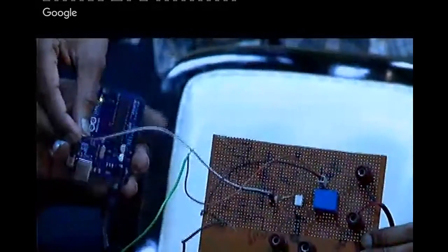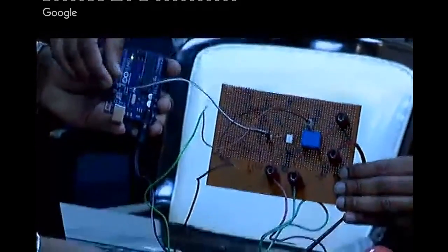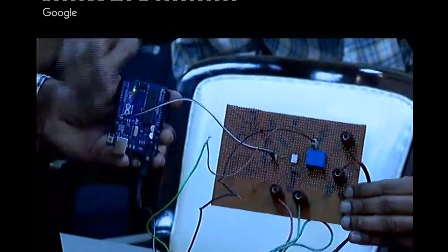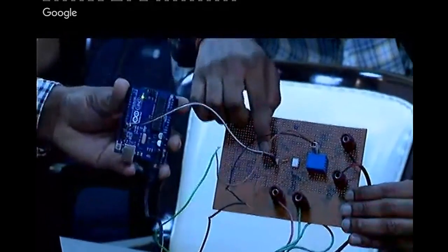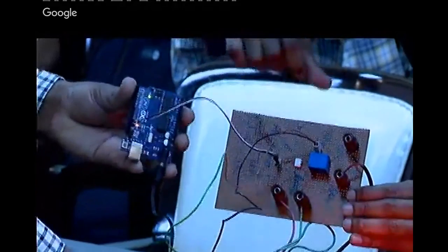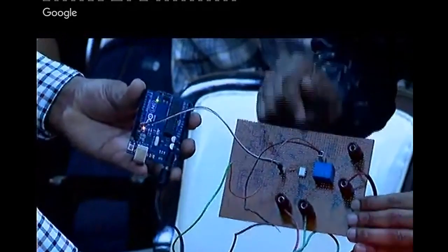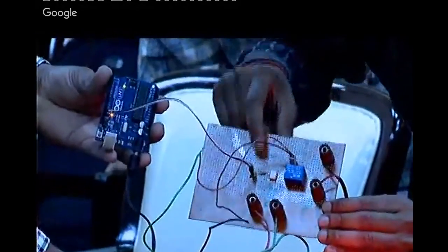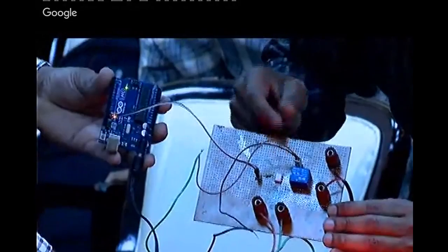This is for input voltage, input triggering, controlling from the Arduino, and it is from the 13 number pin. The black one is the ground, and the white one is from pin 13. It gives the input signal to the optocoupler at pin number 1, where the IR LED is. It turns on the IR LED, then the IR LED gives infrared triggering to the optocoupler's photo transistor at pin number 3 and 4, and the photo transistor turns on.